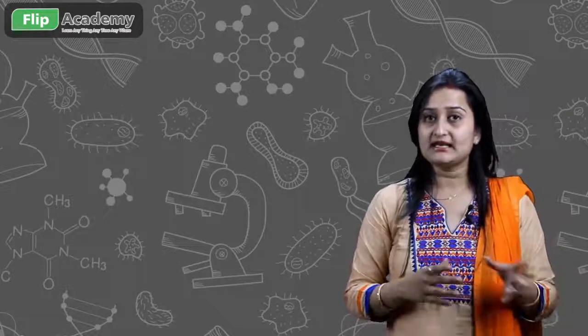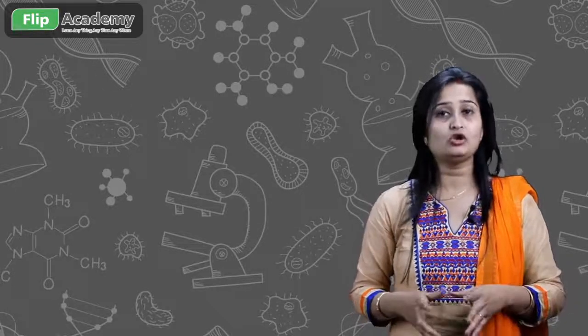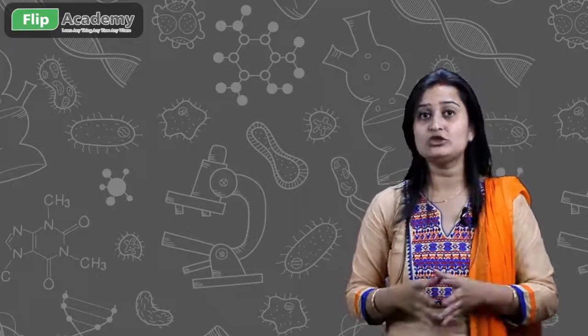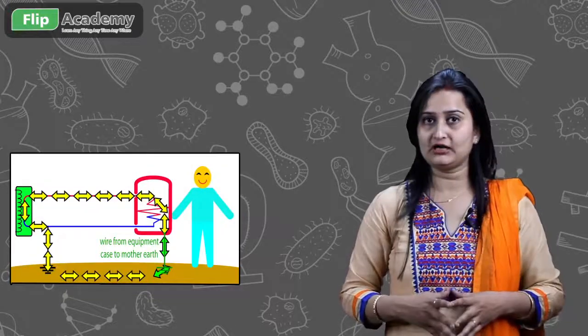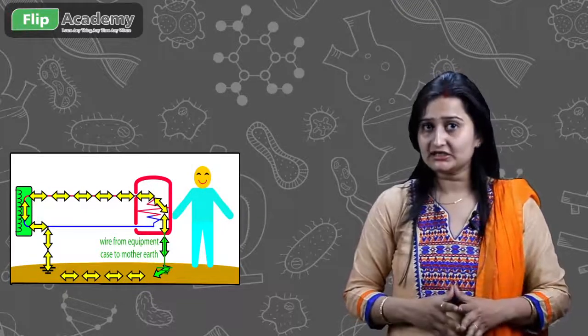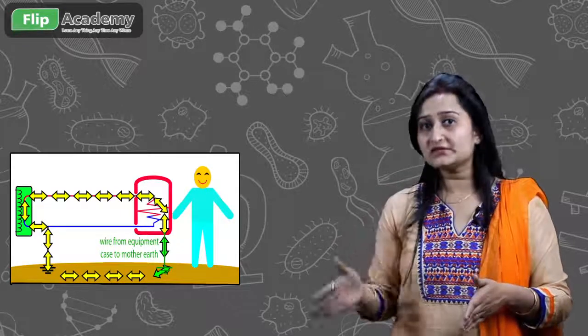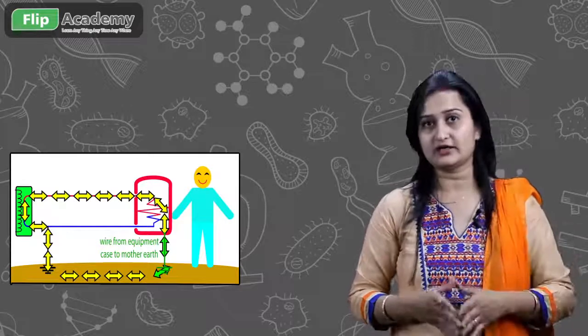In the case when the live wire touches the metal casing of the appliance, the current always follows the low resistance path. The earth has zero resistance. So when the current passes through the metal casing of the appliance, the current does not follow the path towards the human body, but it follows the path towards the earth wire.